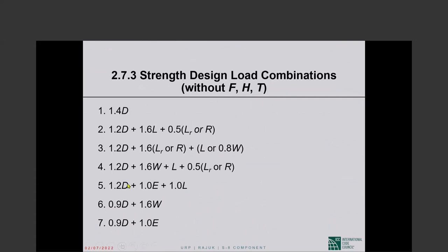Two of the load combinations have earthquake effect E in them. This I call the additive seismic load combination. The gravity causes negative bending moment at a support section. Earthquake also causes negative bending moment. If we want to figure out the largest negative bending moment at that section, we will use that load combination. Gravity adds to the effects of earthquakes.